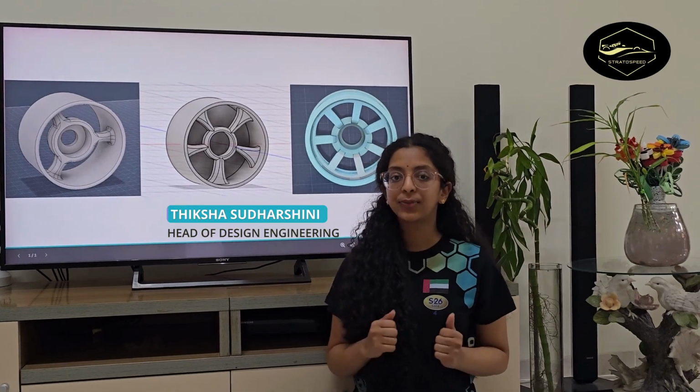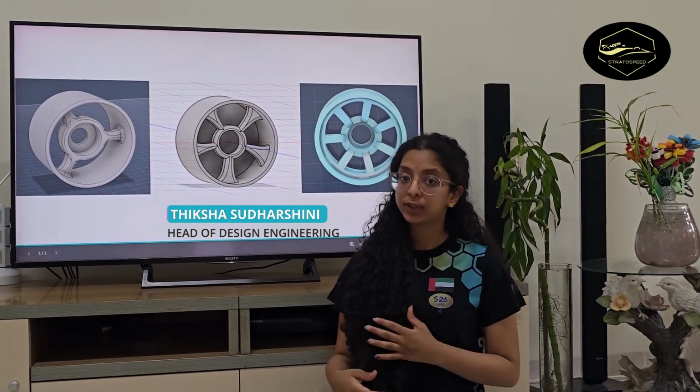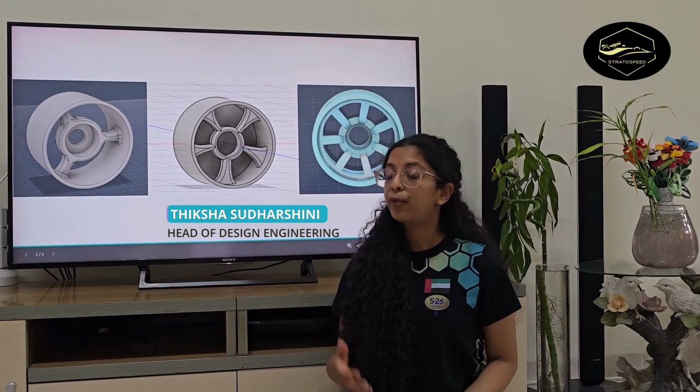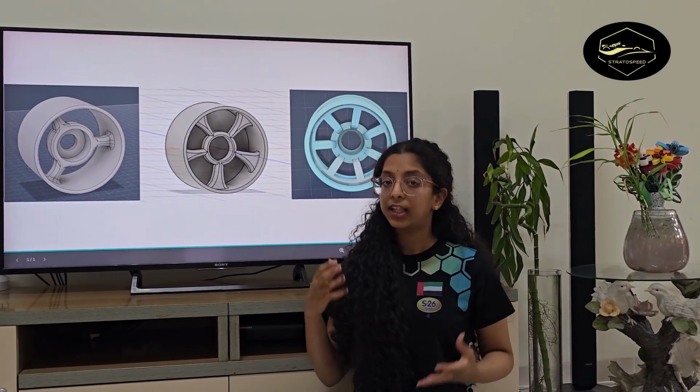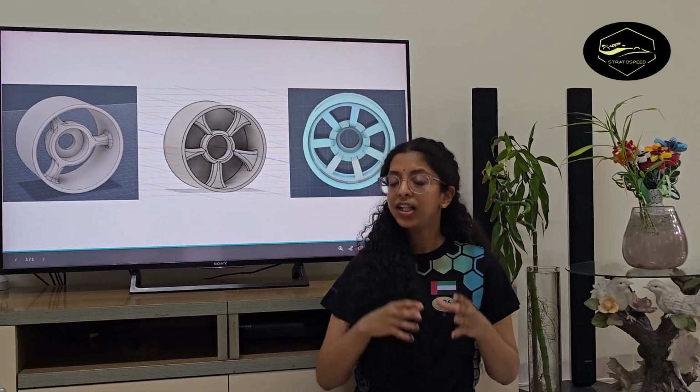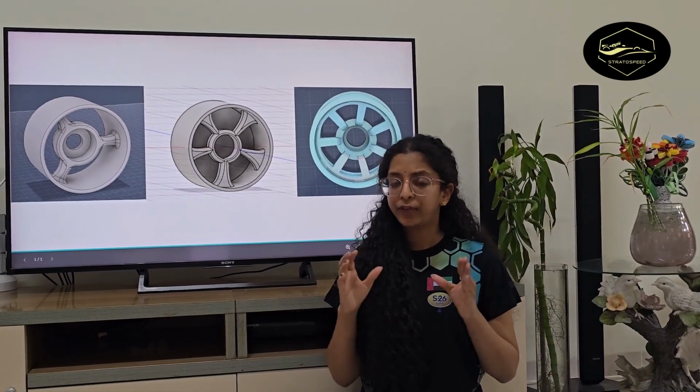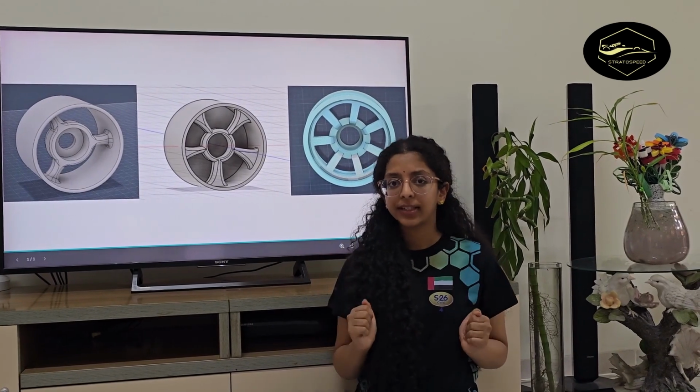One of the first things we tackled was the wheel design, because wheels are more complicated than they look. When a wheel spins up from a standing start, it needs energy to start moving, and the further mass is from the center of the wheel, the more energy it takes. So getting the wheel geometry right was really important for acceleration.